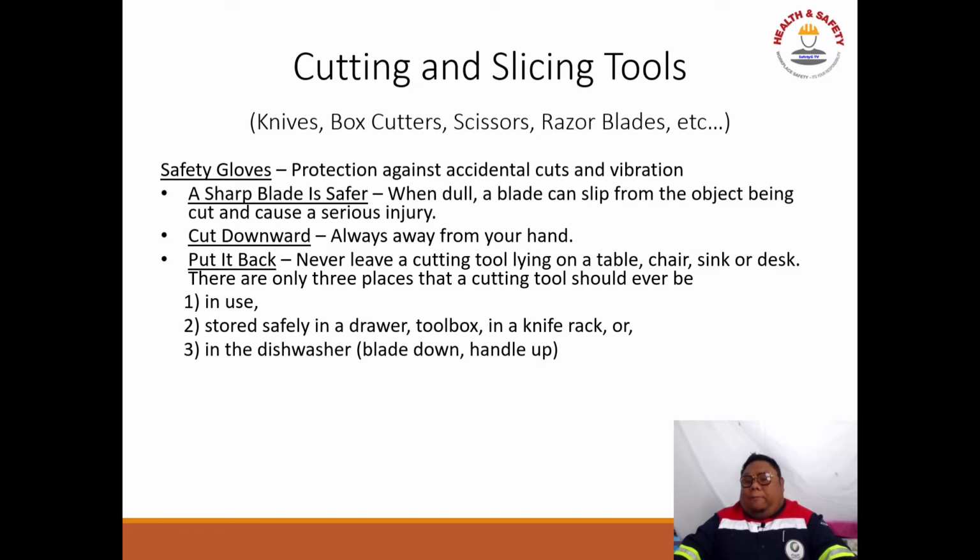I worked previously and witnessed, during cable splicing for high voltage termination, a technician who did not use gloves while slicing the cable and cut his forearm badly.